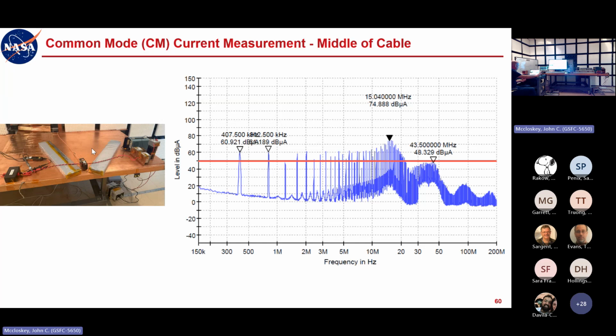But when you're at frequencies where the cable is electrically long, and it depends on what school of thought you come from, but a general rule of thumb is when it's a 1/10 of a wavelength. Some more conservative schools say 20th of a wavelength, or maybe even 100th of a wavelength. But if we go with a 1/10 of a wavelength, it means that the current and voltage distribution will not be constant over the length of the wire.